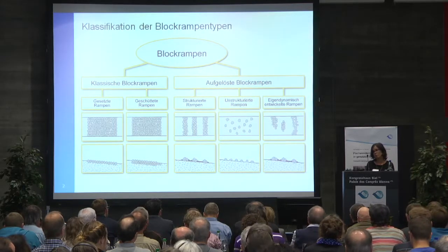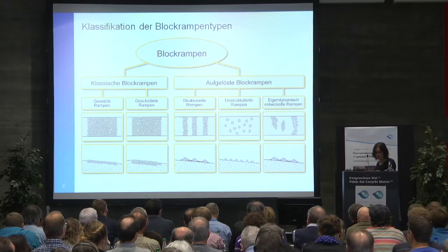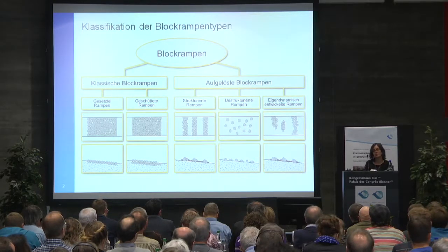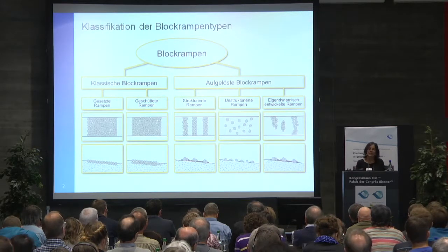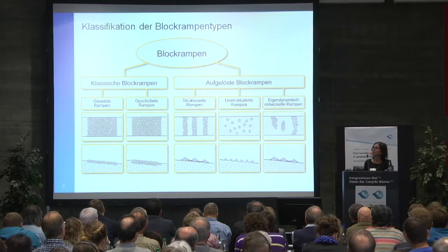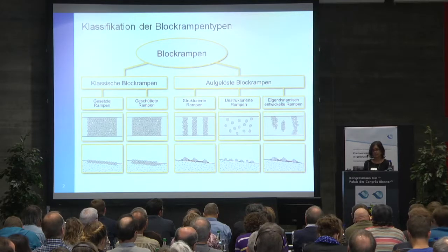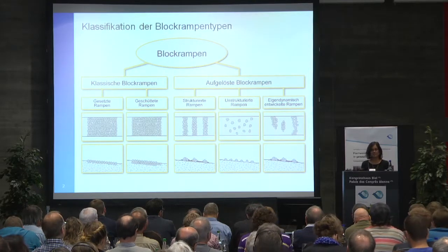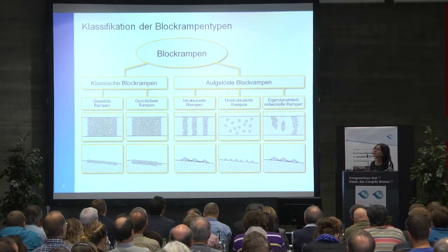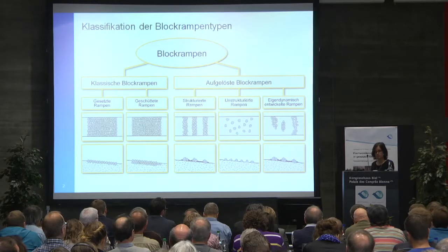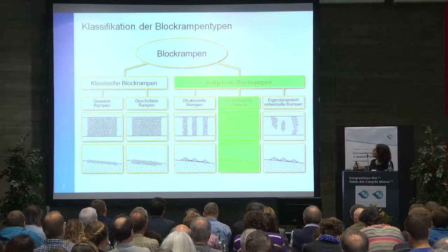And so this is a relatively good behavior in case of an overload. They are not totally destroyed in case of an overload, but they are adjusted. And this is an advantage for flood cases. But rock ramps are not fishways for upstream migration. First of all, we want to protect the bottom of the river against erosion to ensure that it remains stable during floods.